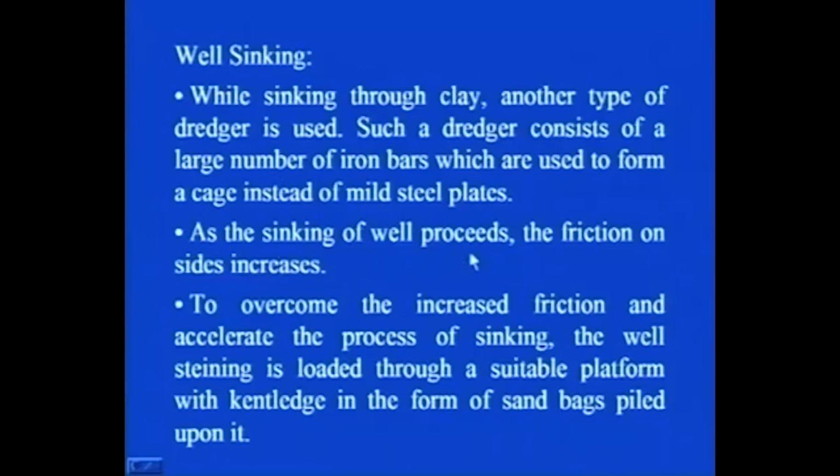As the sinking of the well proceeds, the friction on the sides of the well increases. Now it is not good for the sinking procedure. So you have to overcome this increased friction as well as accelerate the process of sinking. For this purpose, the well steining is loaded through a suitable platform with kentledge in the form of sandbags piled upon it.